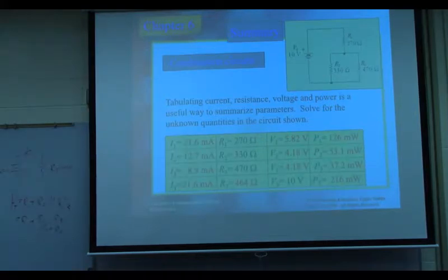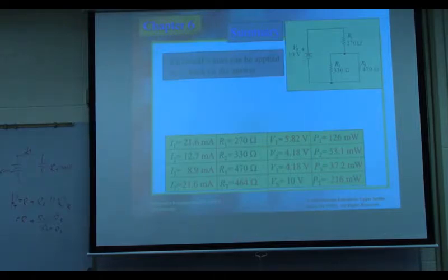Okay, the meter may be broken. These numbers may not be accurate. Right? So that is troubleshooting. Everybody should know the techniques. So this is Kirchhoff's current law applied to check the sum of the currents must be equal to 0.